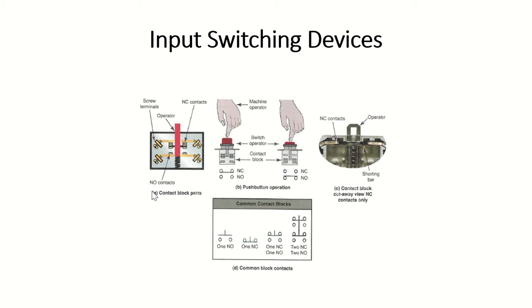This slide here was to let you guys know that you typically have to order these contact blocks. When you're ordering this equipment, the operator and the contact blocks not always necessarily come together. On some types of equipment they may, but more than likely you'll have to order those separately, and you're going to have to understand that you can get these contact blocks in many configurations.